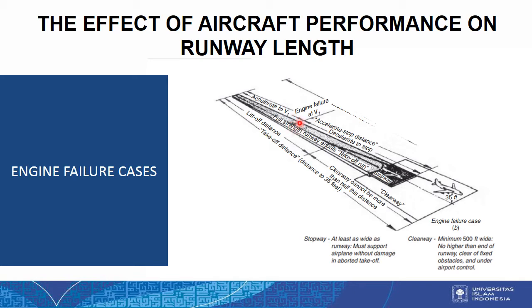So if there is an engine failure below V1, the pilot has to cancel the takeoff. The aircraft goes to the stopway, and if the engine failure is above V1, the pilot has to continue the takeoff here.